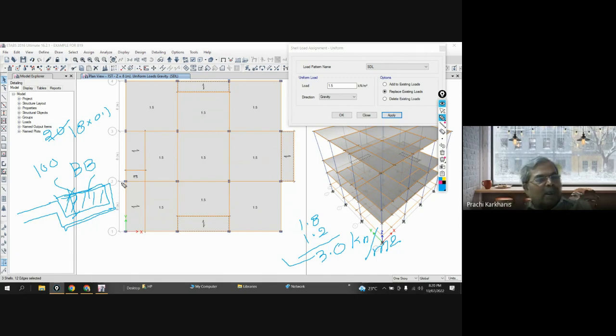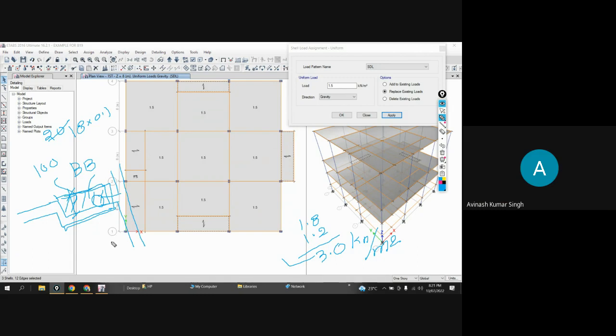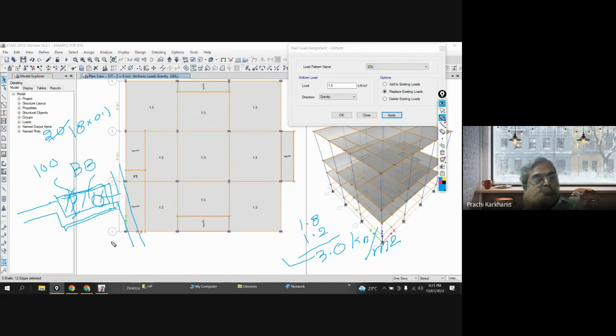तो उसके लिए, already in concrete, when you are going for concreting, a sunk has been provided, and that sunk is by 100 so that after providing a trap over here, let's say this is your trap which is going back, and this will be connected to your plumbing services. तो the drainage facility will be created, क्योंकि यहाँ आपका वॉशिंग वगैरह कुछ एक्टिविटी होता है ना, तो पानी कहाँ जाएगा सर? ड्रेनेज में ही जाएगा सर, हाँ, तो उसके पाइप के थ्रू। प्रोविजन अगर नहीं करेंगे तो नहीं जाएगा ना। हाँ सर। तो वो प्रोविजन करने के लिए there is a sunk part of 100 mm, 150 mm, 200 mm. That is the discretion of the architect.